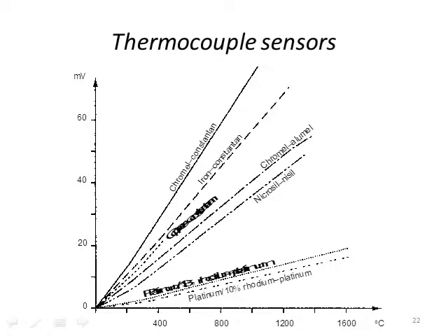And these are the calibration plots for different types of thermocouple sensors. You can see on the x-axis we have the temperature that we want to sense, and on the y-axis we have the voltage dependency. In all of these, which are measured characteristics from a data sheet, they're extremely linear, so we can essentially ignore the T1 minus T2 squared terms from the Taylor expansion.